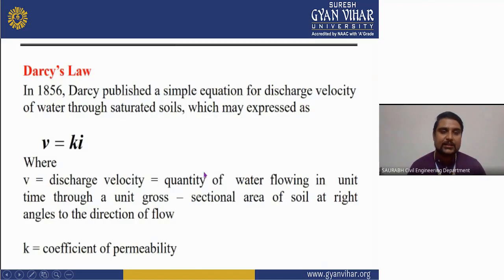Now we will see Darcy's law. What is Darcy's law? In 1856, Darcy published a simple equation for the discharge velocity of water through saturated soil, which may be expressed as V equals k i.